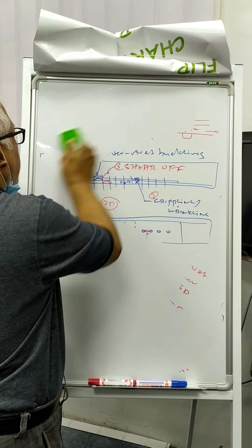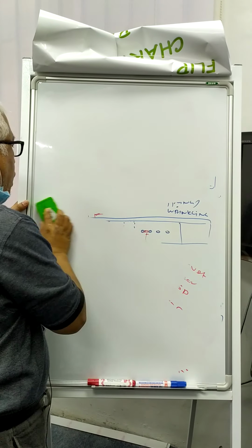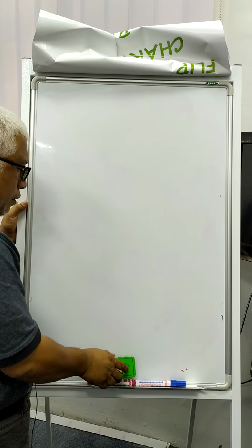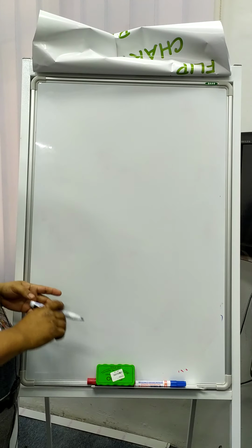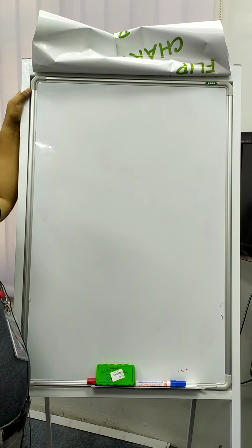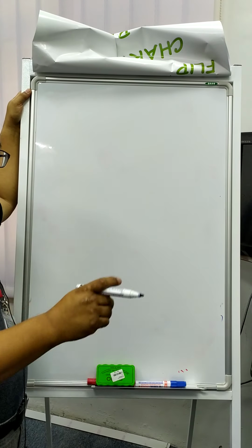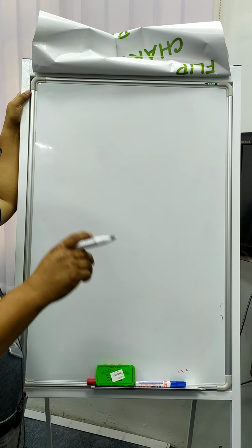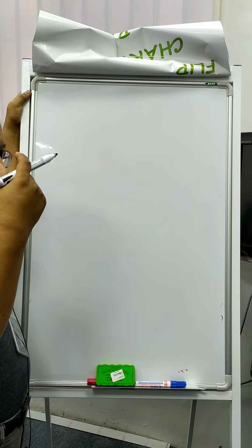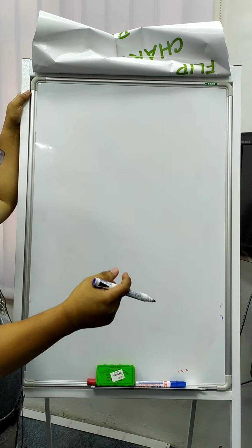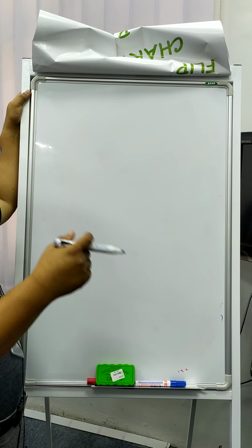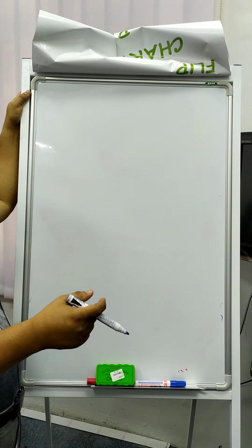So what is the problem when you do a repair, mod or anything on the aircraft? The certificate of airworthiness of the aircraft is no longer valid until the repair is approved. Repair also can be a modification. Once you repair and maintain the aircraft, the current certificate of airworthiness is no longer valid until the repair is approved by the organization issuing the certificate of airworthiness.